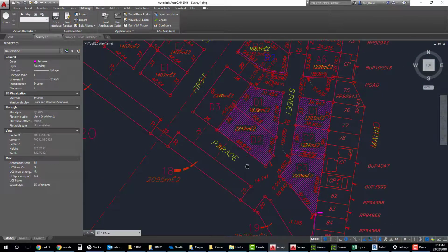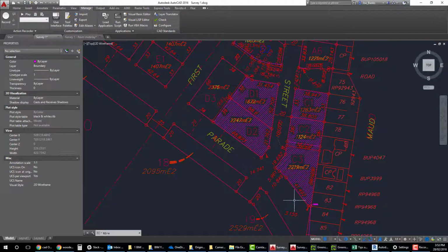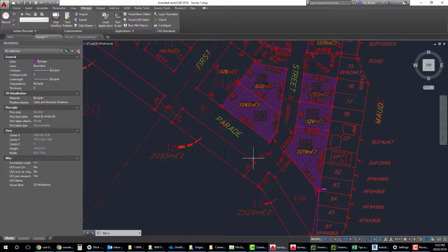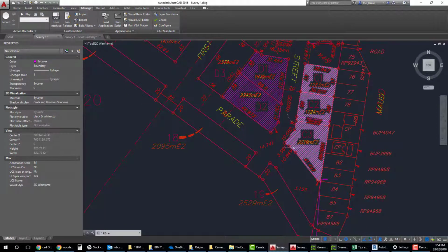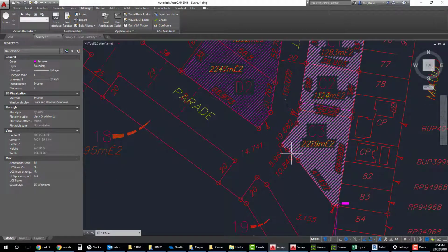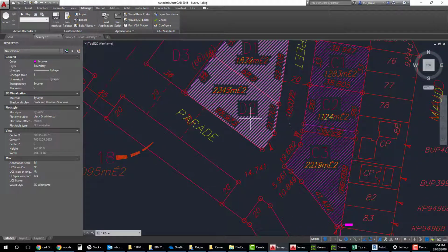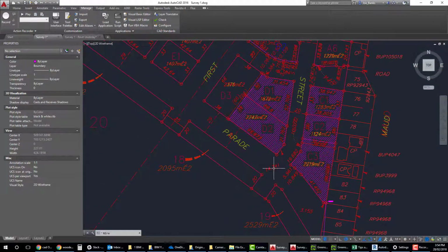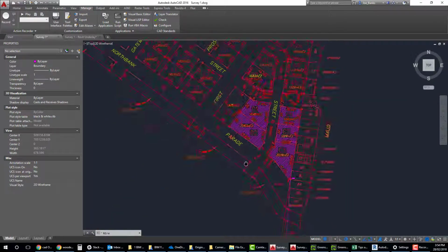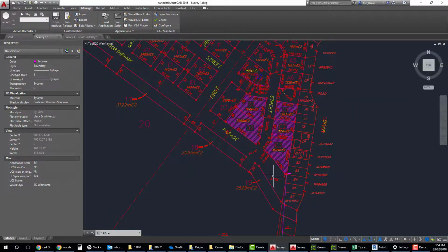The important thing is that the local datum that you're using is something that can be reproduced by a surveyor with relative ease. So I try to stay away from a screw-in curb or some sort of site feature that could potentially be demolished, or something that's right in the middle of the site that's going to be in people's way. You want it to be off to the side and easily reproducible for all of your consultants and any other surveying work that needs to be done.